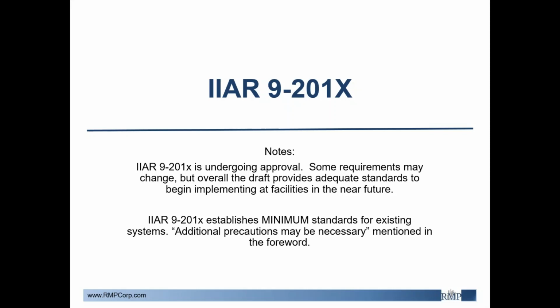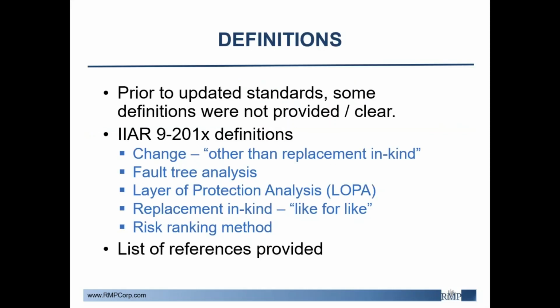Within this, IAR 6 is referenced. IAR 6 is the standard for maintenance, testing, and inspection. So IAR 9 references that in terms of the frequency and what kinds of inspections. We'll probably do a separate webinar on IAR 6, but essentially IAR 6 is taking B109 and B110, which were traditionally guidance documents, and rolling them together into a standard that will now be for ammonia refrigeration. So we're taking some guidance and now moving it into a standard that will be ANSI approved.